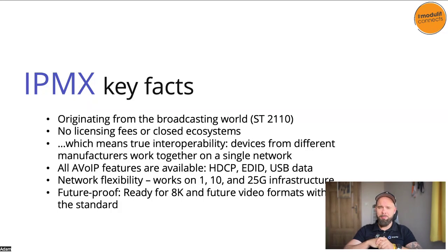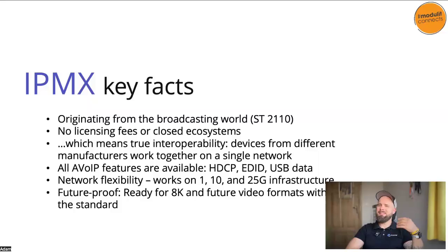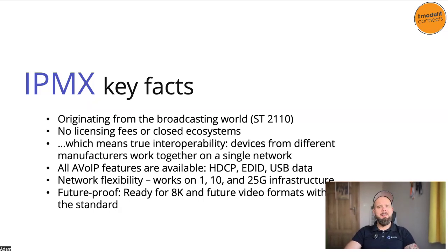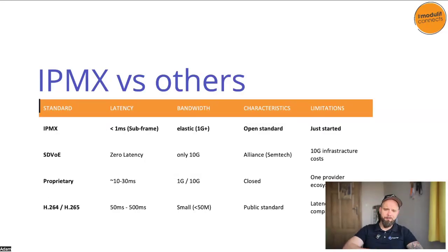I hope so, because it brings some nice features to the table as well. First, it's flexibility. A 1 gigabit network will work with it because we can set the compression level. 10 gigabit, of course, and even 25 gigabit network infrastructure is supported here. If we don't want any compression at all, we can transmit an 8K signal without any latency. So it's the most future-proof standard you can get these days.